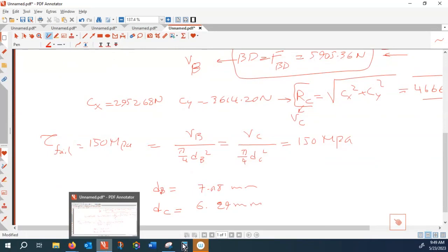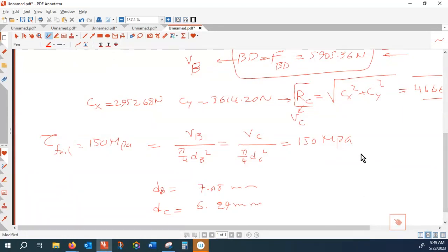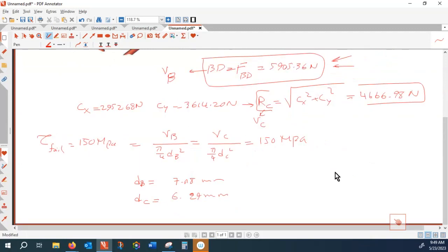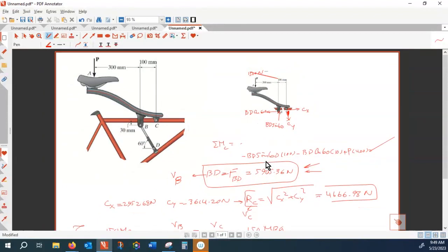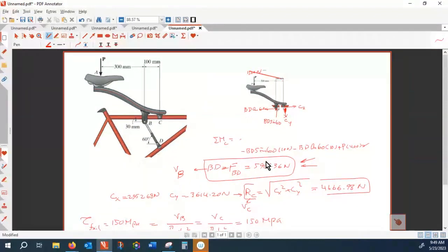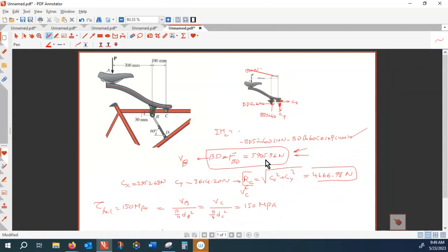So that one is assuming someone a heavyweight person, I mean, 1,500, that is someone almost 150 kilograms. Someone 150 kilograms sitting on that, you need a pin of diameter of 6 millimeter. Anything thinner than that is going to cut.